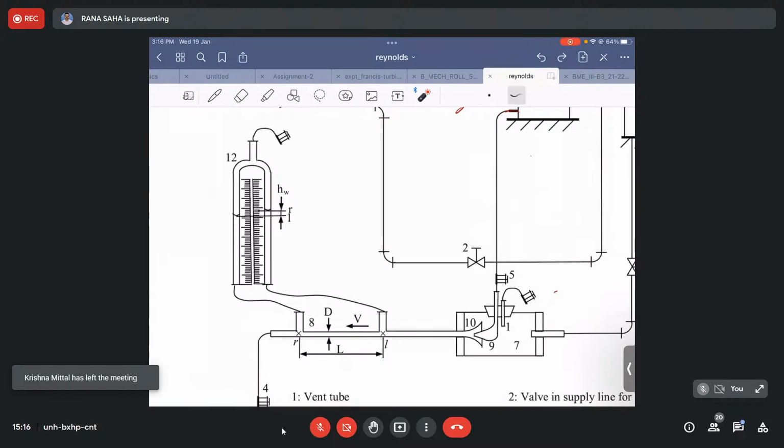The simple U tube manometer is the one that is oriented like a U. Then there is the inverted one. Why are we using the inverted U tube, and the manometric fluid here is air? Because the difference in head between the two tappings is very small. If you use a high density manometric fluid, you may not be able to distinguish the difference in head, because that difference will be very less. If you use a lesser density manometric fluid, then possibly you can get the difference in reading.